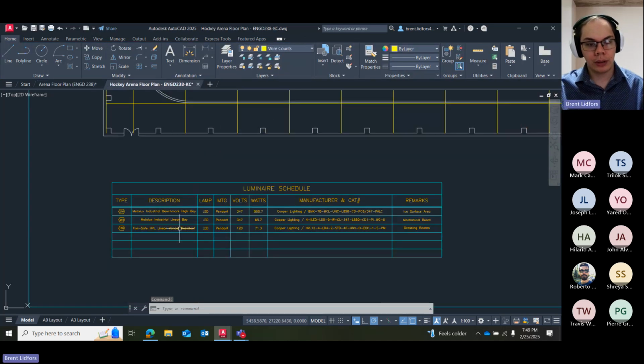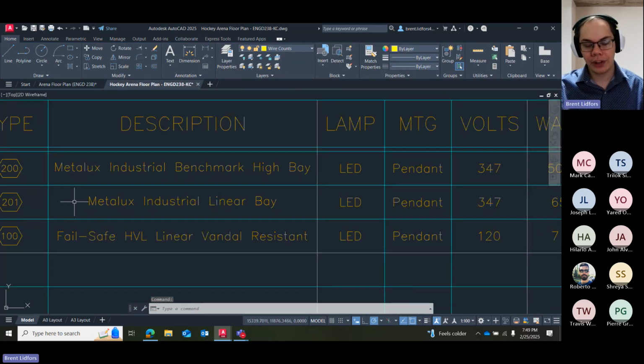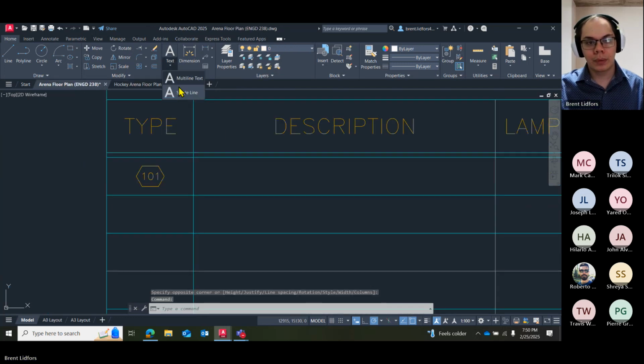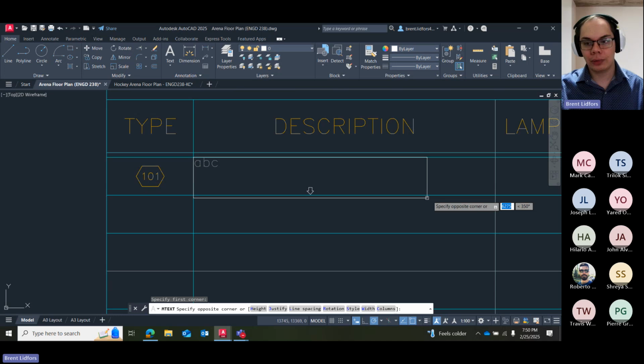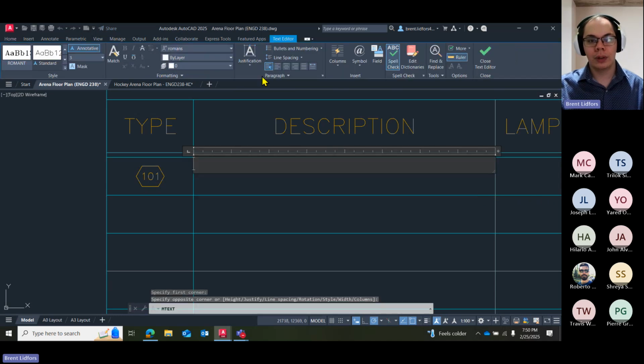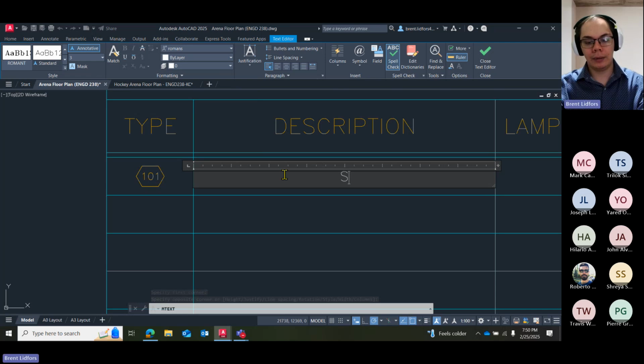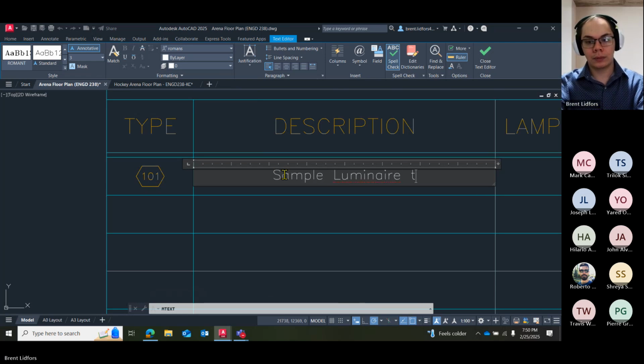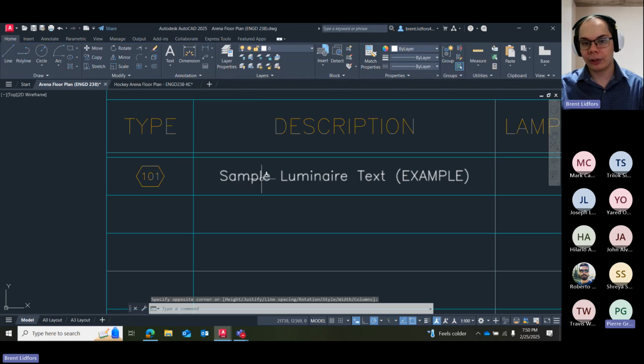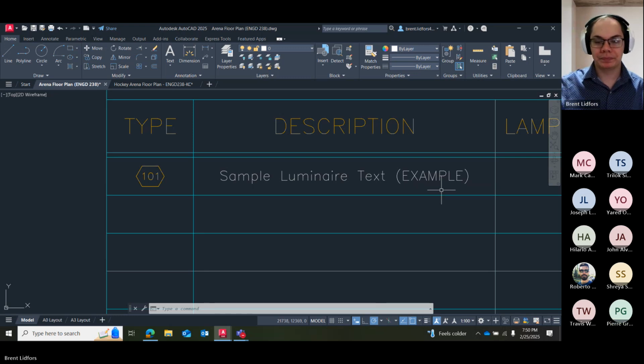Let me double check. Yeah, this looks centered. There's even space on both sides of the text. So I'll use multi-line text, 2 corners, switch this justification to middle center, and then put in my text, and then it's centered in the box. Yeah. Thank you. I didn't realize there was the drop-down menu there. Oh, yeah.